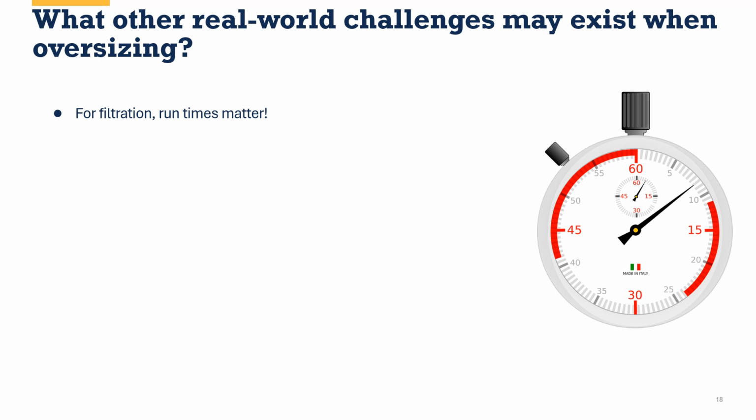Filtration will matter. So let me ask you this. Does the filter do anything if no air is moving through it? No, of course not. So we want to have good run times. Now, somebody said earlier, Dan, what's an example of a good long run time for a heat pump? During peak cooling season and peak heating season, we'd like to see that thing running about 90 to 100% of each hour. That's honestly what we'd really like to get.